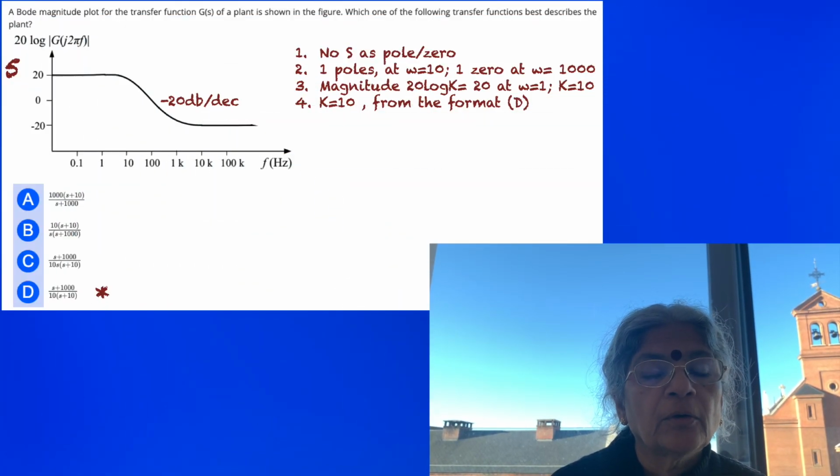We again have a log magnitude curve, or what may be called a Bode plot. And we see that it plunges from plus 20 to minus 20, but the plunging starts off at a frequency of 10 hertz, and stops at 1k, and in between, at a frequency of 100, it becomes 0. So now we have many things here.